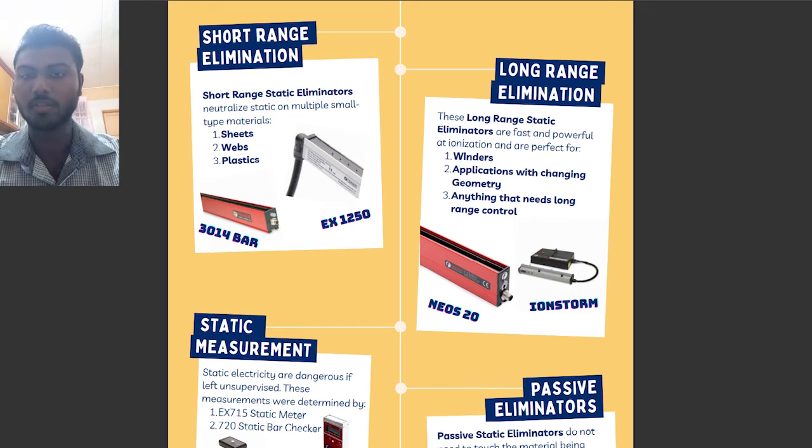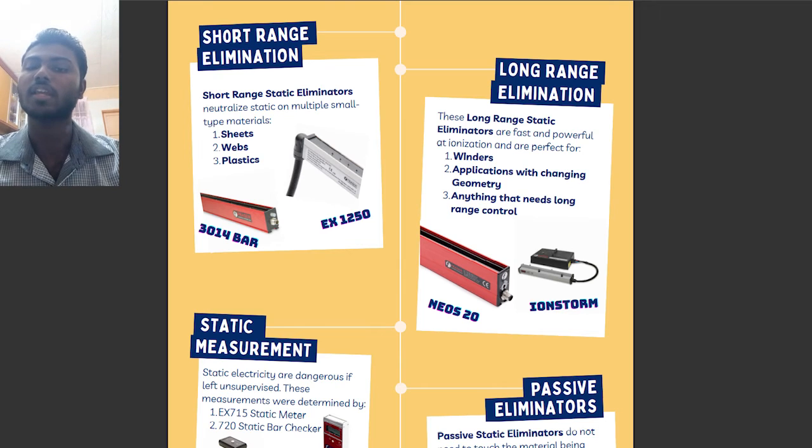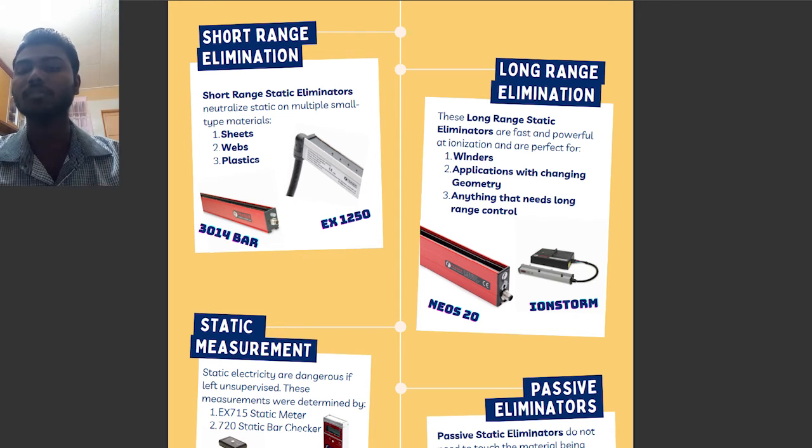When this happens, the product cannot be cleaned by neutralizing the static charge, nor by blowing it off. The products need to be wiped with a wet cloth or with solvents. The lesson here is to neutralize the charge and remove the dust immediately after extraction.